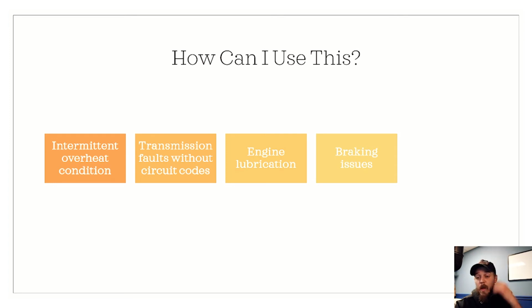Braking issues, correct length of brake lines, an ABS valve, a solenoid valve that's shifting too quickly or too slowly or not fully shifting. We can run into issues there, where traction control systems don't work properly, where we have one-wheel lockups, where we have a lot of issues. Understanding hydraulic principles helps us better diagnose these.